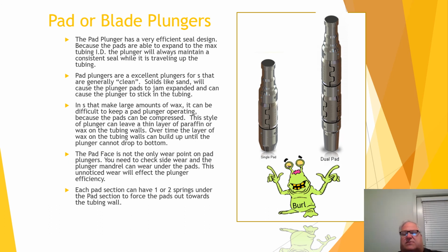If you don't, look at a solid plunger, run a little longer plunger, and it'll last very well. You have fewer moving parts, and typically your cost of operations is going to be a little bit better than running a pad in a higher rate well, because you're not going to be pounding on them so hard. In a low rate well, 100%, great application.